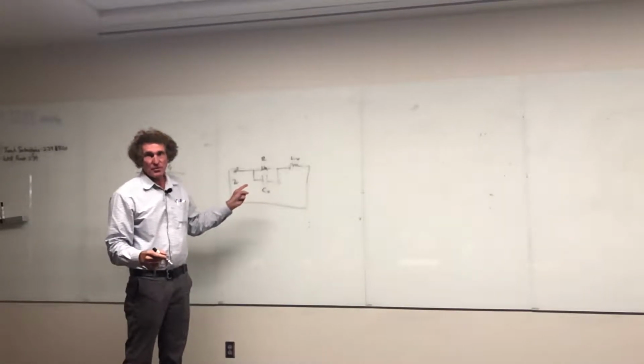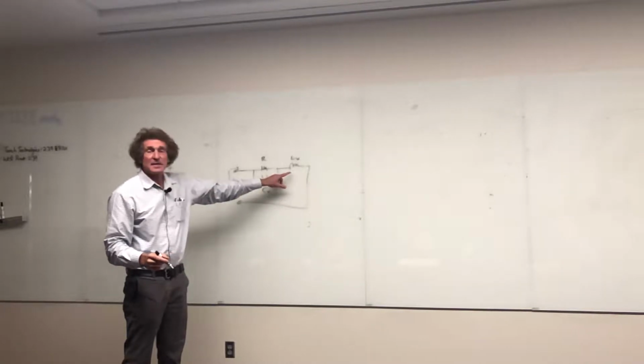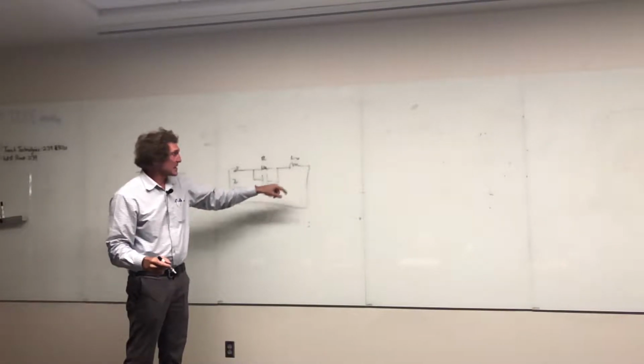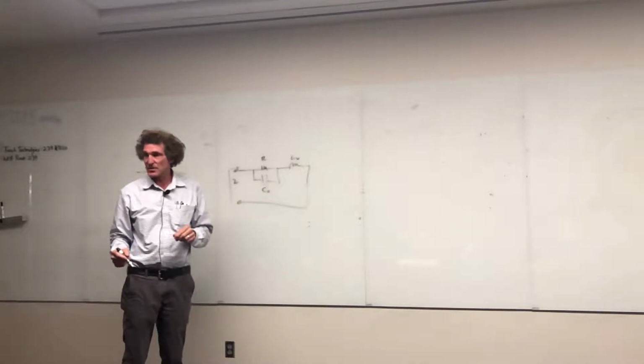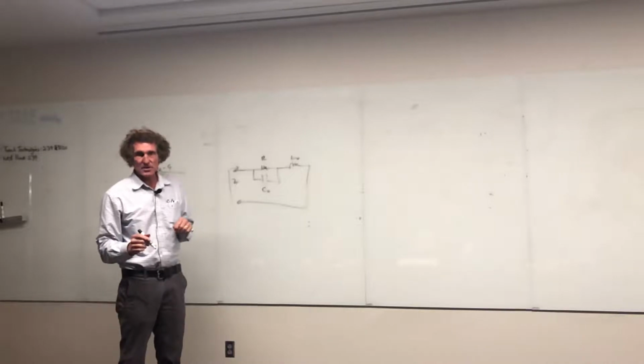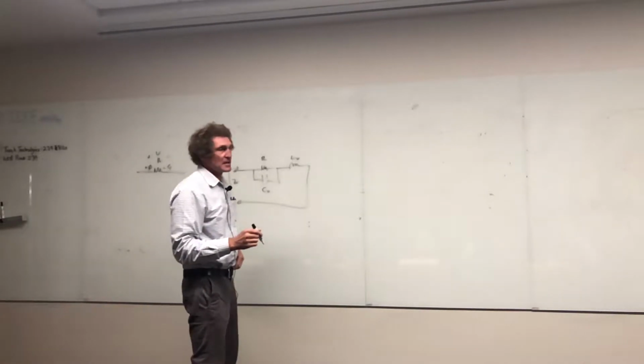In truth, you know that the inductance here is a function of frequency. We just figured that out, right? The inductance is a function of frequency right here, which means this model kind of breaks down. Also, the capacitance is a function of frequency. So this is just a first order cut at it, but they pretty much look this way. I've done this a lot in EMC, seen things.